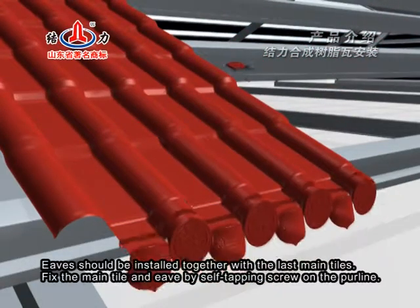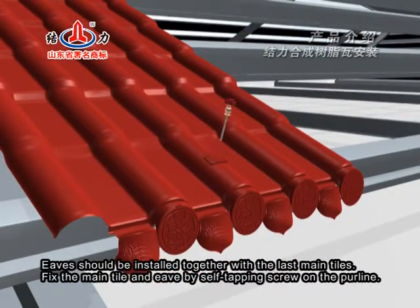Installation of eaves. Eaves should be installed together with the last main tiles. Fix the main tile and eave by self-tapping screw on the purlin.